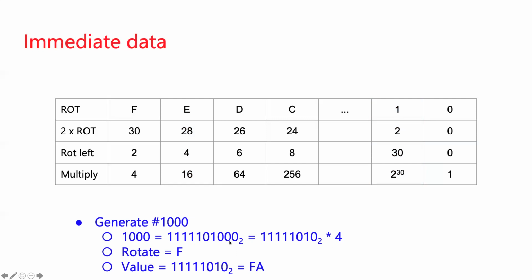I just chopped off the 2 low order bits and put a times 4, since those were zeros anyway. And now I've just got 8 bits that I need. That's 8 bits of non-zero values, so I could specify that as my value. Those are my 8 bits. And then I just need to slide those to the left by 2 bits to get 1,000.